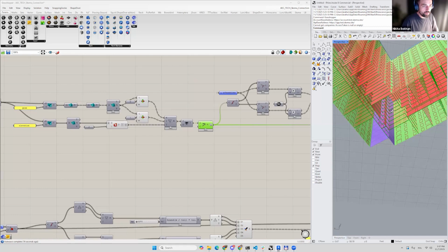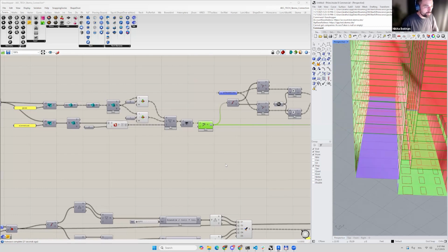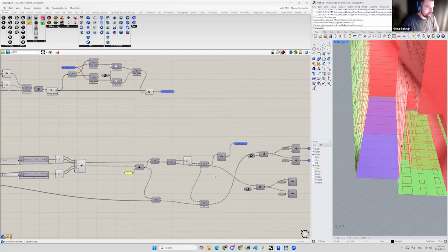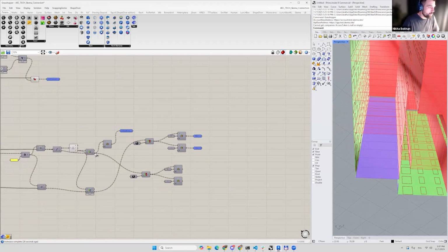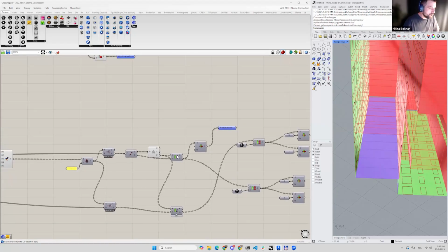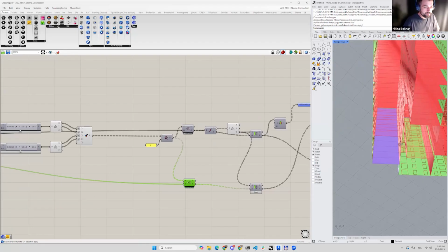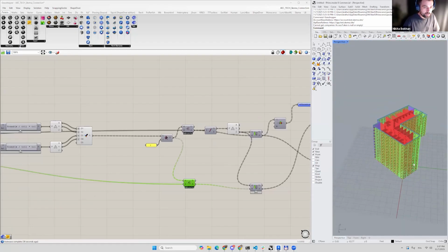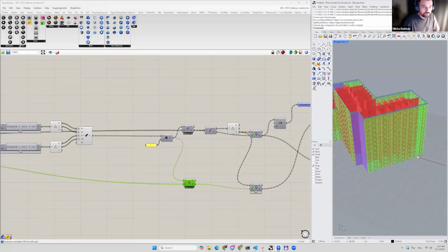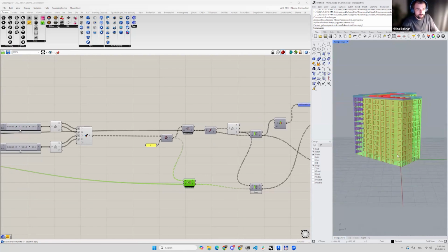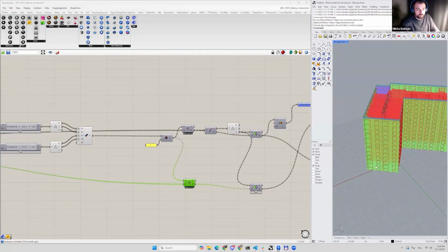So now we have all our interior and demising walls, and on another hand, we have all our facade lines grouped by belonging to a particular unit. I group all the walls which have the same X and Y position in order to have this vertical stack of all the walls. My goal here is to have the surface of each wall.